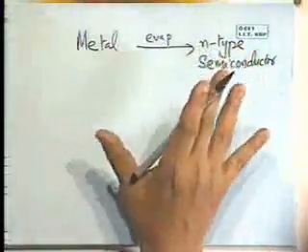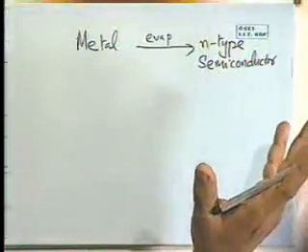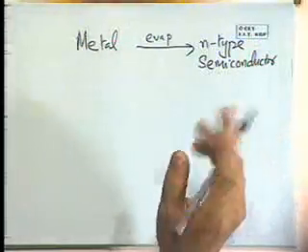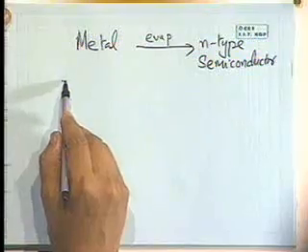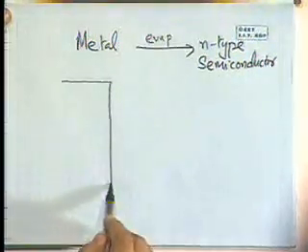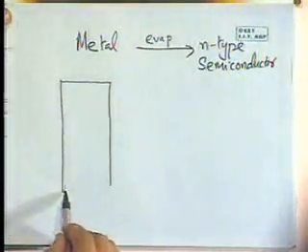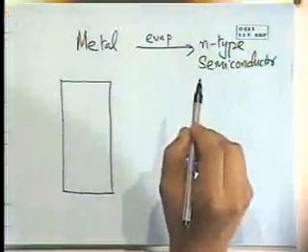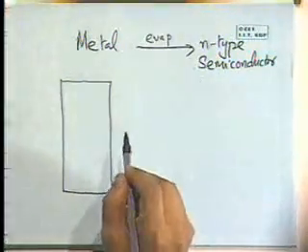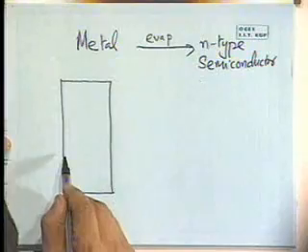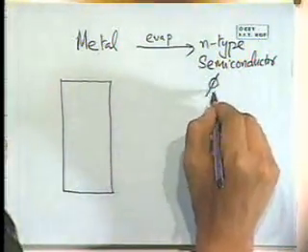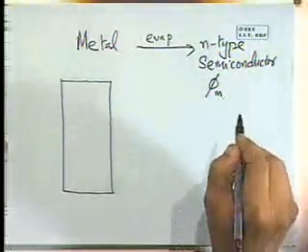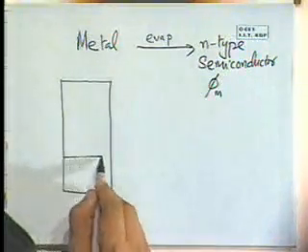You could do the same argument with a p-type semiconductor too, and the essence of the argument is essentially the same. And what we do is we begin by looking at the contacts before they are brought into contact, two situations, one where the metal is not yet in contact with the semiconductor, and the other case where it is already in touch. And the specific example that we'd look at is where phi m, which is the metal work function as we've seen before,